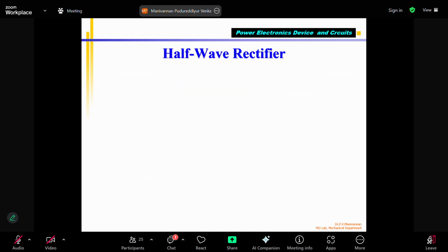That's one thing. Next, we are talking about voltage regulation. If I supply a voltage from a DC power supply, this is my VDC. VDC we have computed for a 5 volt secondary, it should be 1.6 volts, correct? This should remain constant as long as my load is 10 ohms. Suddenly, I reduce my load to 0.2 ohms. If I change it, what will happen? The voltage will fall.